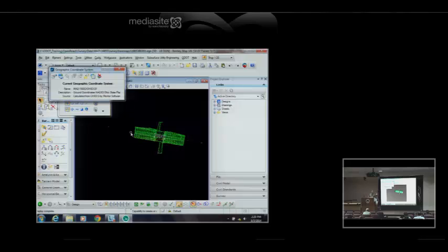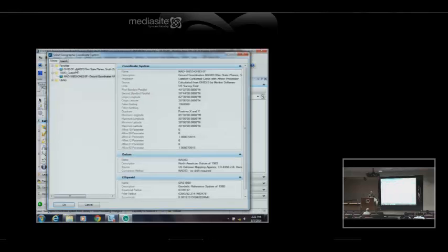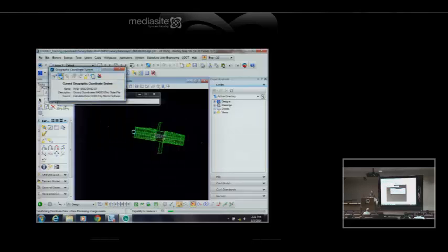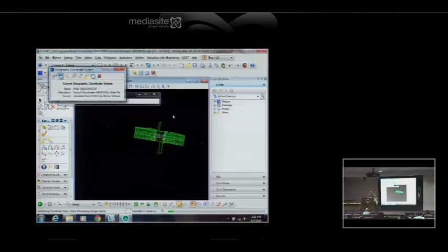So if I have a client that says I want ground coordinates, once I've made that custom GCS, it did move for me. So if I go to my library and I copied the Ohio to favorites, so I don't have to navigate through it. So which one? I'm on the ground right now. If I pick the grid and say OK, say reproject, we should see it move. It just moved for me just now. I did that yesterday.